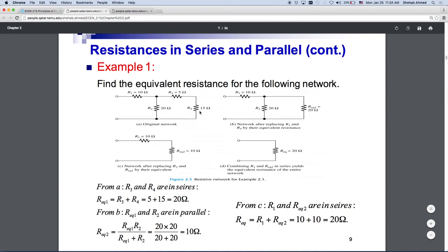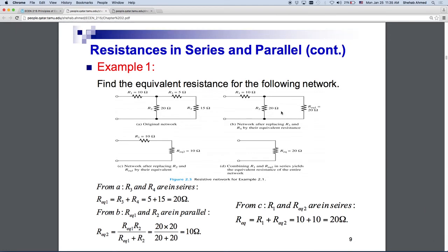So you found the source current, and then you went one step back, and you know that the source current is flowing here. I asked you what is the current flowing in this resistor, what would you have to do? Go one more step back. Expand again. I know this current is coming into this 10 ohm resistor. It's going to be distributed between these two. These two happen to have the same resistances, so the current coming in will be divided among them equally.